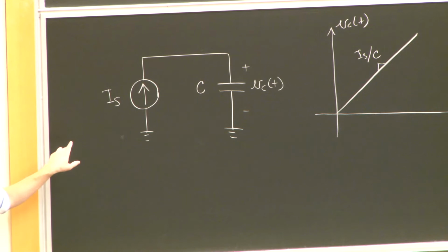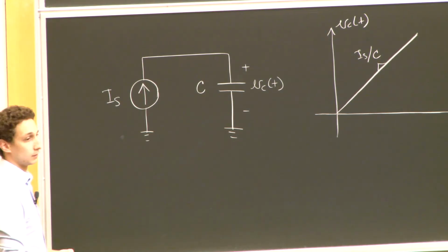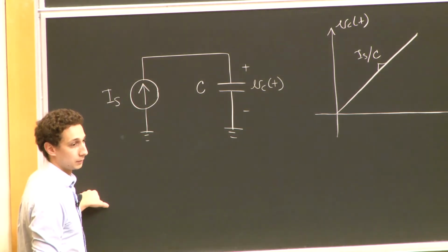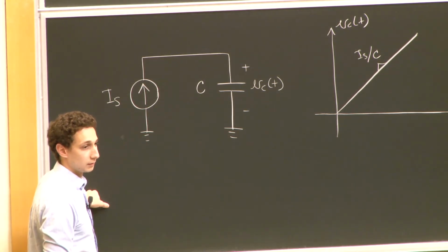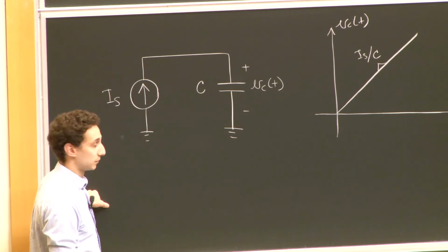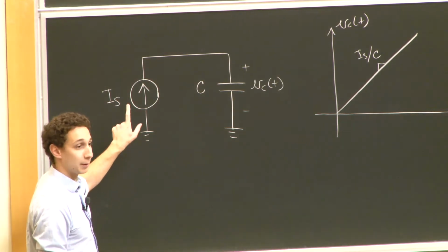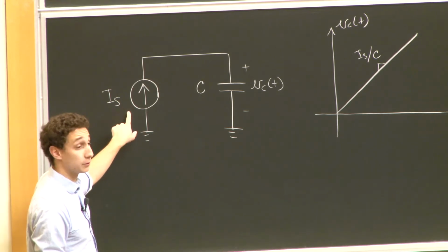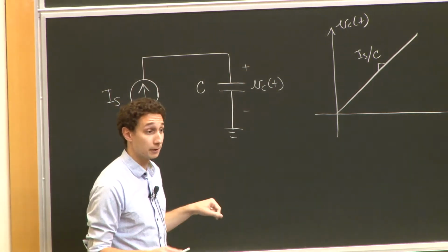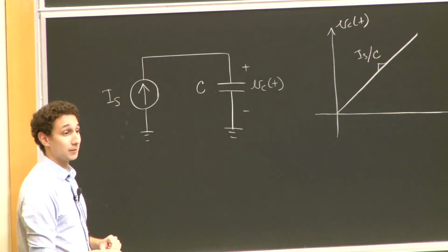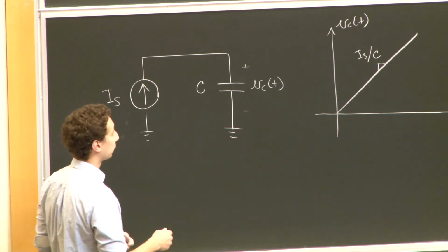Now, how could I turn this general idea into some oscillation, some periodic waveform? Yeah. So the voltage would stop when it's equal to a certain point. So that means we can set the VTH for VC1 as that threshold. So the suggestion is this will stop after a certain amount of time, but I never told you what's inside of this current source. As far as you know, this is perfect, and this will go on forever. Yeah. If you reverse the current so that you get a downward slope? Yeah, what happens if I reverse the current?